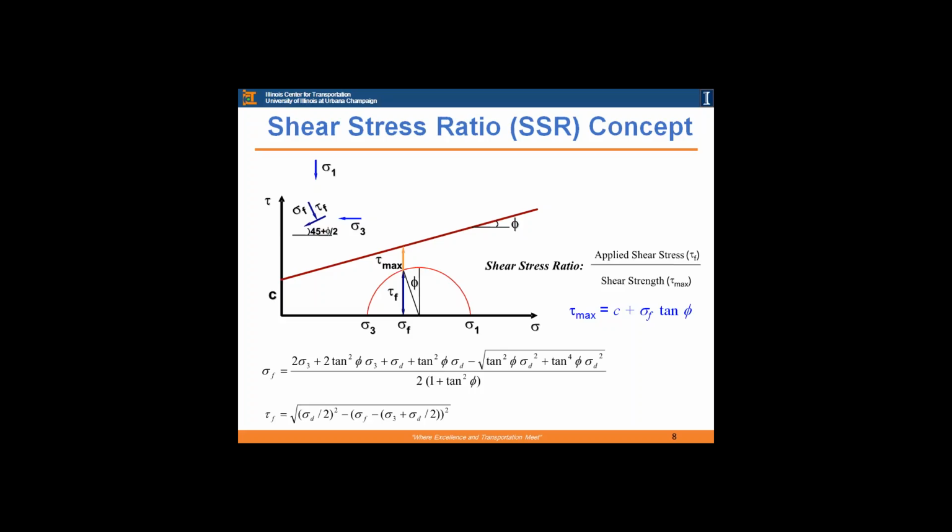The question that I want to ask you is, consider a situation where you have a very high modulus material. You're applying very high stresses, but your tau max is average. Would you expect this material to accumulate a lot of permanent deformation? Say that again. A very high modulus material, and you are applying a lot of stresses to it, high deviatoric stresses, but average tau max, which can happen, since modulus and strength are not correlated to each other. The average tau max is similar to one of your materials in here. Would you expect this material to develop permanent deformations?